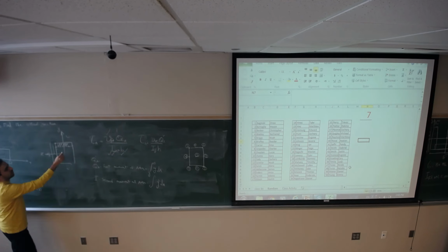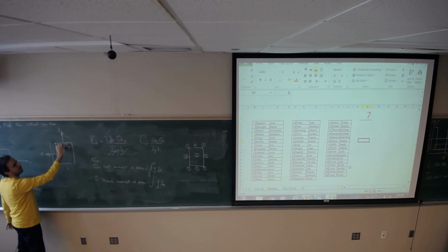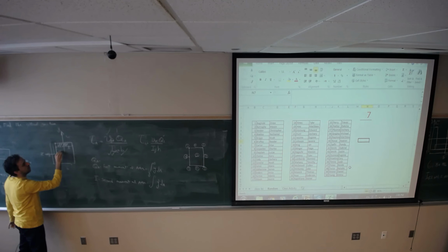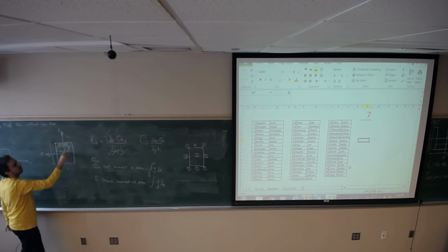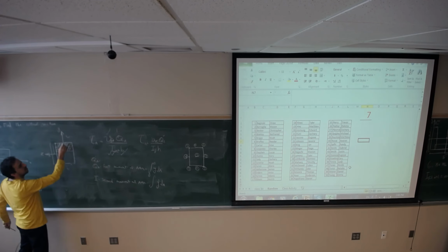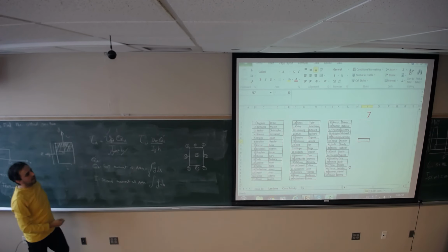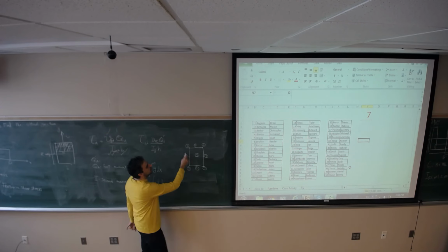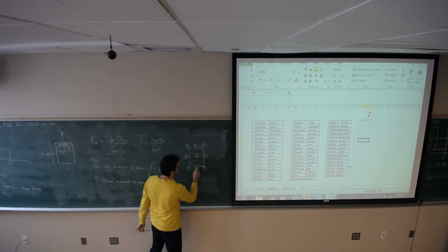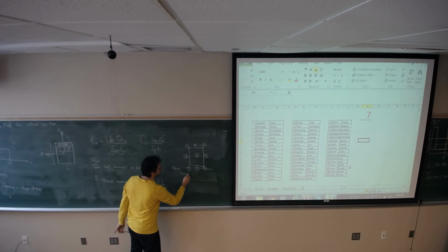So if I choose point A here, Q is going to be the integration about this section. If I choose point B here, the cross section is going to be greater. So if I pick a point on this line, Q is going to be 0, because there is no area for Q. So all points on these two lines are going to get 0 transverse shear.